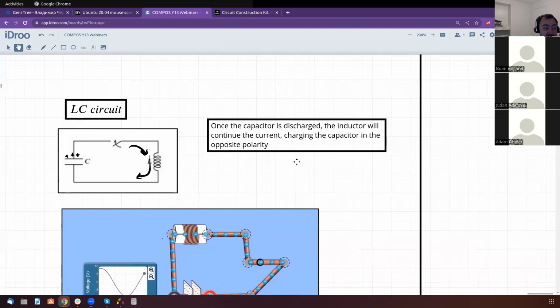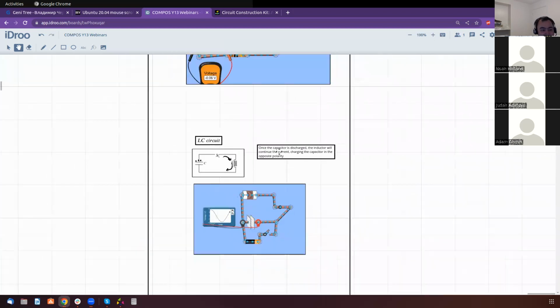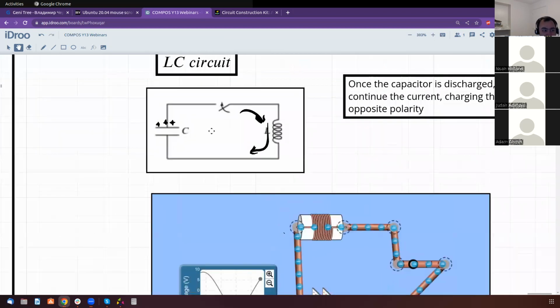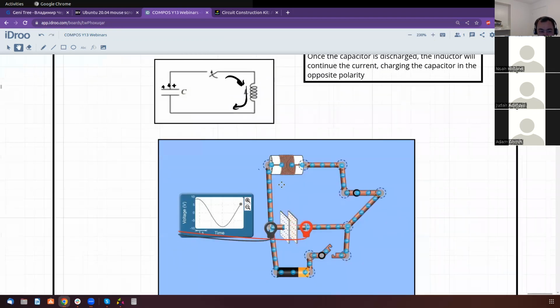Not really an AC generator because it will die out. The oscillations will die out because here you have an exchange of energy without losing anything. So it's like a pendulum. Can you use a pendulum to generate AC? Well, not really. But if you keep charging the capacitor, I'll show you how an AC behaves in such a circuit, which is quite interesting.